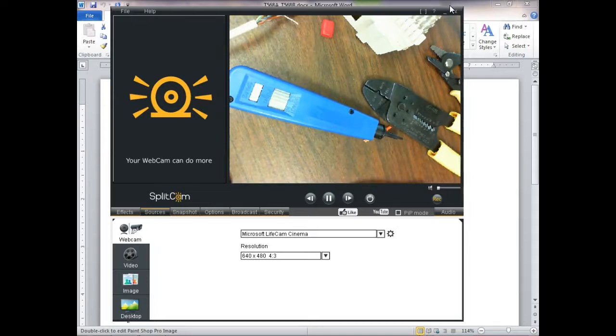Orange-white, orange, green-white, blue, blue-white, green, brown-white, brown. This goes green-white, blue, so this is a crossover cable. So this is what Siemens gave us with our new PLCs. Crossover cable. And of course that's shielded, that's STP, that's industrial Ethernet cable right there.